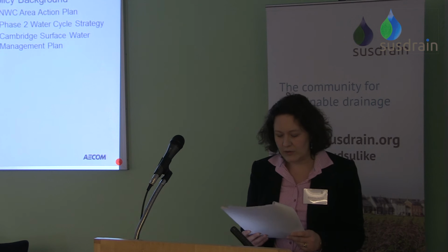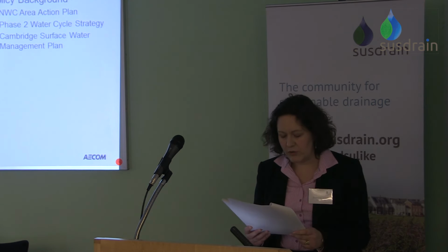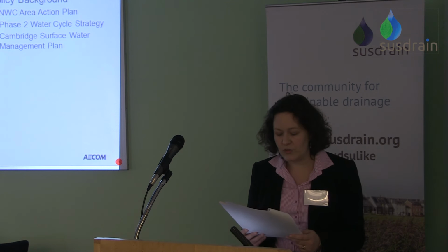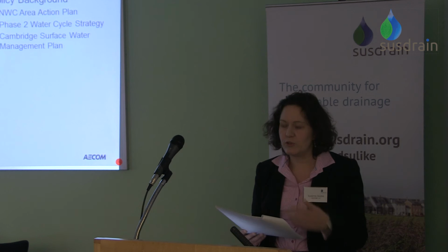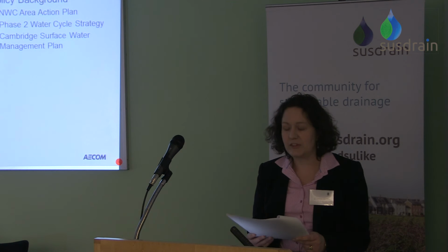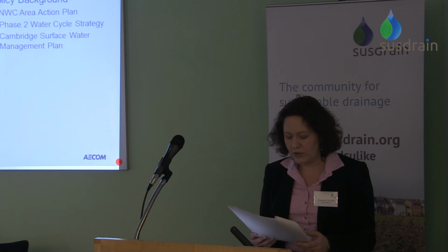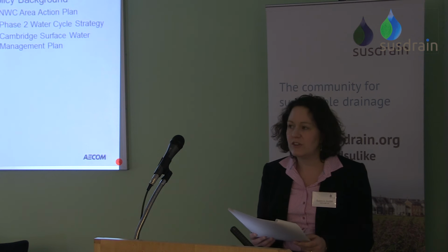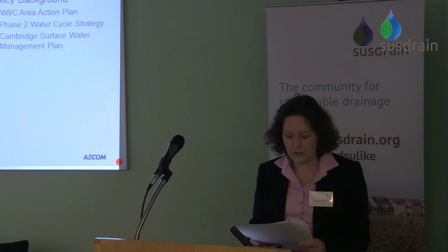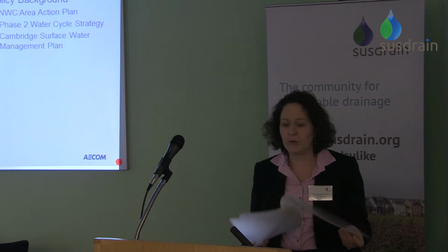Of particular note, we were required to design surface water as a SUDS system to reduce overall runoff volumes leaving the site, to control the rate of flow, and to improve water quality before it joins the Wash Pit Brook, which is the watercourse that flows through the site. The development needed to be an exemplar of sustainable living, able to accommodate the impacts of climate change. It should incorporate water conservation measures to significantly reduce potable water consumption. And as Emma and Stuart mentioned, we had to achieve BREEAM Excellent and Code for Sustainable Homes Level 5.